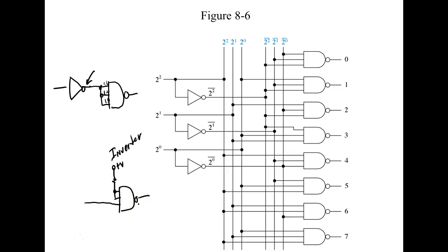What would that circuit do? So these right here are always high. So this serves as an inverter. What advantage does this one have? Yeah, so my gate's only driving one load. So you'll see this done a lot, which one is most convenient, which one are you pushing on your power supply, right? You'll see pull-up resistors used a lot. What's a pull-up resistor? This is a resistor that we use to guarantee a high.